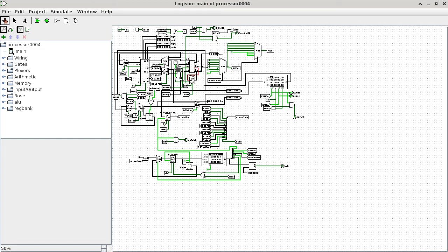So in the RISC design, they try to simplify the hardware, they try to simplify the number of instructions, and they try to simplify the number of addressing modes and whatnot. So the idea is they want the computer die size to be as small as possible, to use as few transistors as possible. CISC, on the other hand, is the opposite. They try to make one instruction or one addressing mode for everything that we want to use.